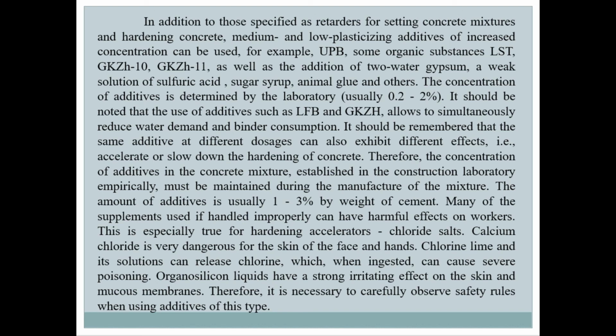It should be remembered that the same additive at different dosages can also exhibit different effects, that is, accelerate or slow down the hardening of concrete. Therefore, the concentration of additives in the concrete mixture established in the construction laboratory empirically must be maintained during the manufacture of the mixture. The amount of additives used is 1–3% by weight of cement.